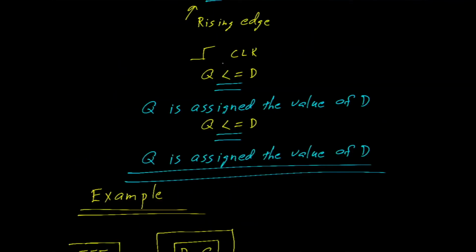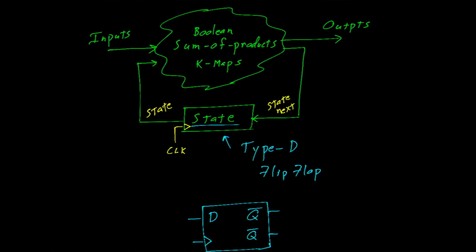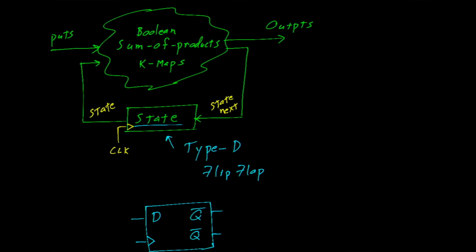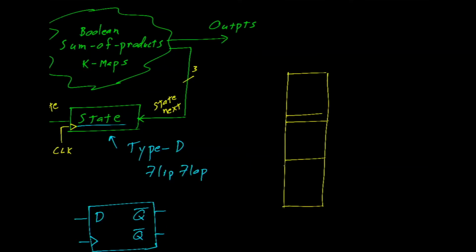Moving back to our state machine, we would likely see several flip-flops tied together. For example, if we assumed that this was 3 lines, that means there would be 3 data flip-flops, which will be sketched mirrored because our signal is flowing in that direction.